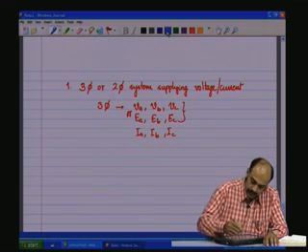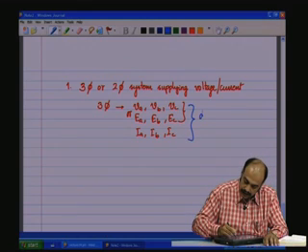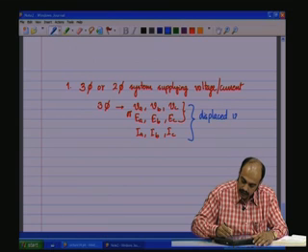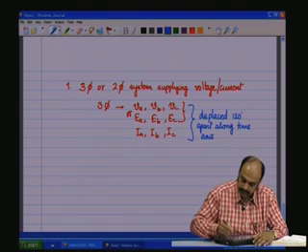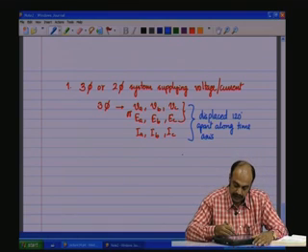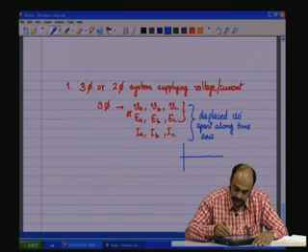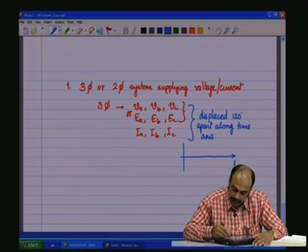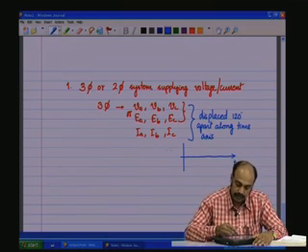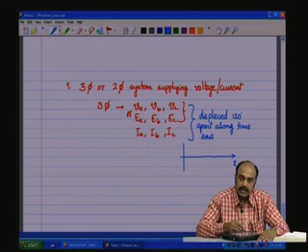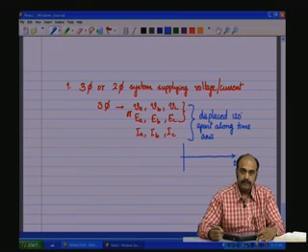Now, these are displaced 120 degrees apart along the time axis, which means the displacement between IA, IB, IC of 120 degrees is along the time axis, which when we talk of as phasors in the spatial coordinates, it reflects as three phasors 120 degrees apart.